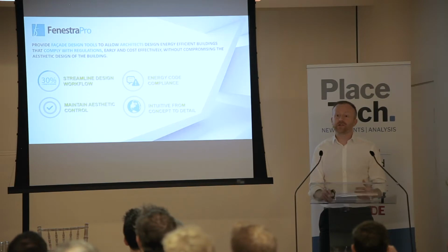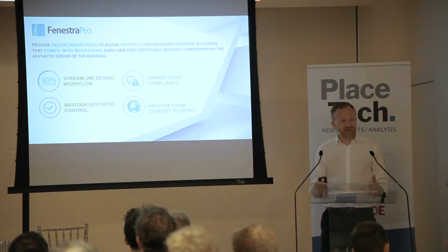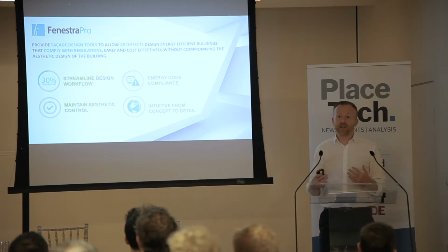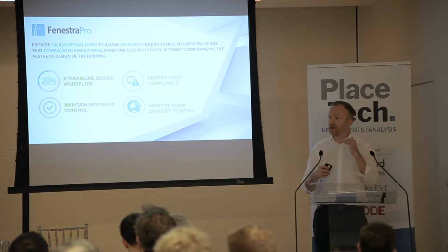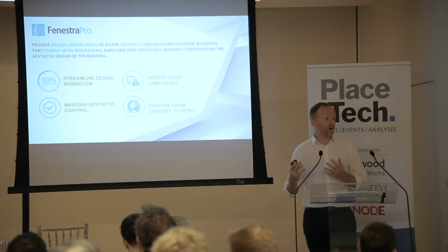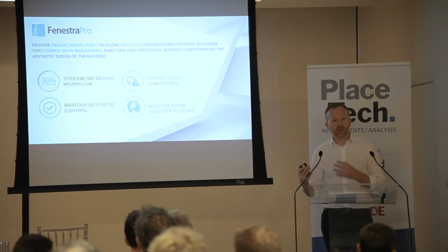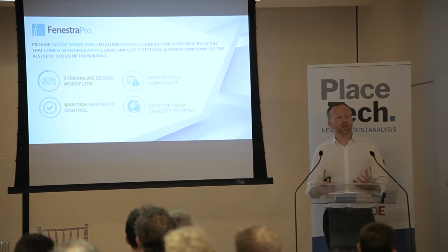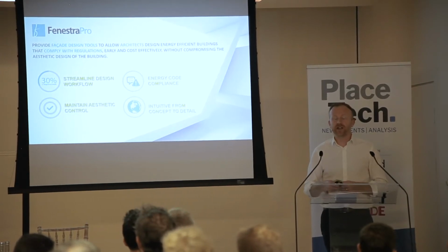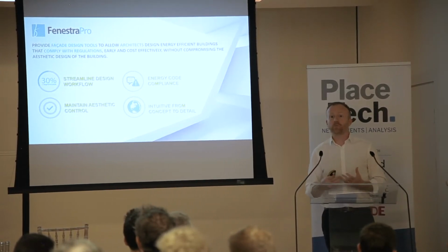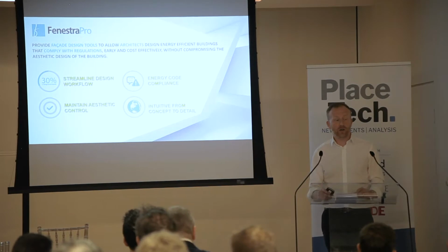So a few benefits of that. We can very much streamline the design process of the facade. If we know we're going to need shading devices, we know the depth of those shading. We know, are they going to be horizontal or vertical? We know what type of glass we're going to use, how much of that glass. And it's not going to be reiterated, it's not going to be reworked, it's not going to change late on in the process. And as I said, that allows the architect to maintain aesthetic control over the process.